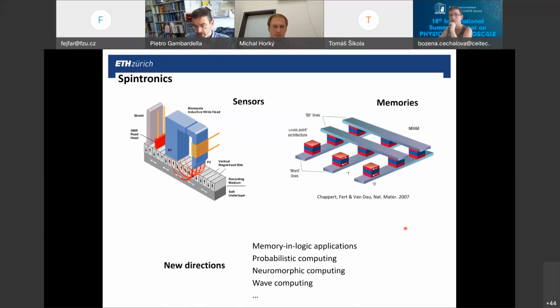But we know, for example, that magnetic multilayers are used in sensors to read the magnetization. For example, this is a track where we have magnetic bits written in up and down domains, the magnetization in each domain representing a 1 or a 0 of a digital bit. And their state can be written by applying a magnetic field with this write head, okay, with an external coil essentially.